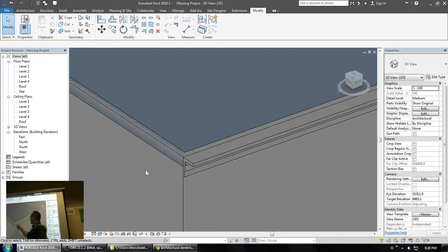I wanted to show you folks how you can make this stretchy extrusion so you understand the process of making a little filler piece for millwork, if you ever have need to do that in the future. Okay, so that is page 9 done. Last thing we're going to talk about tonight is swapping nested families.